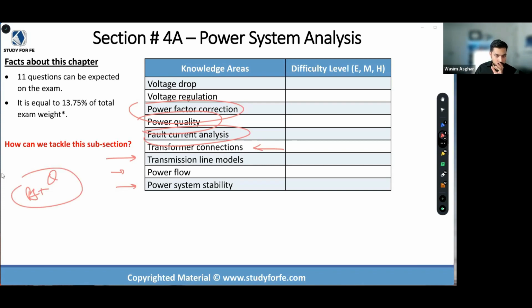Well, that is obviously better than just looking at the power triangle, but then you got to remember that this power factor angle is calculated on the basis of voltage phase angle and the current phase angle. Does this have to be always delta or Y? No, it can be either or, as long as you're correctly accounting for the 30-degree phase shift, right? And remember, we did a couple of practice problems where we did one problem like 2-3 different ways, right?